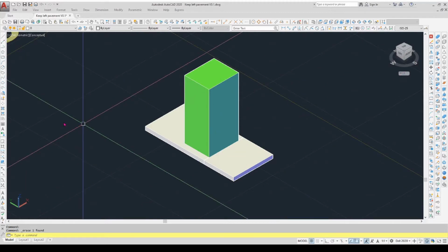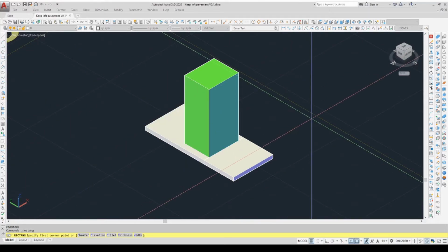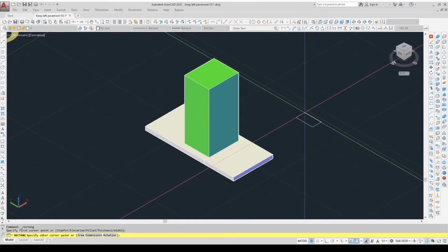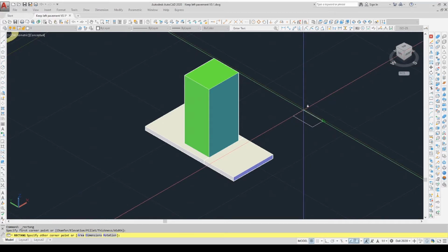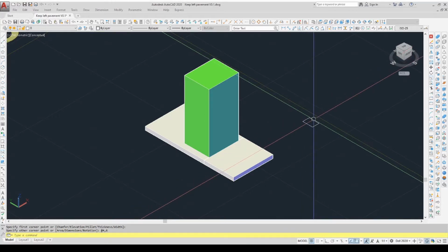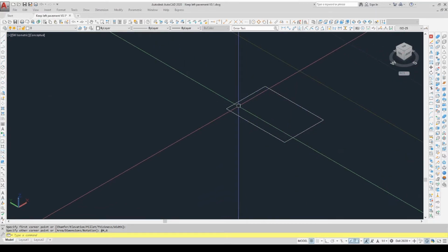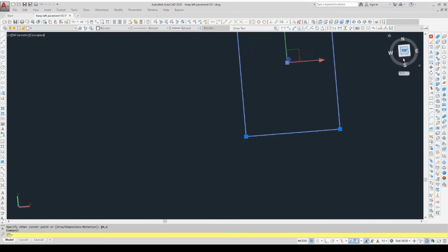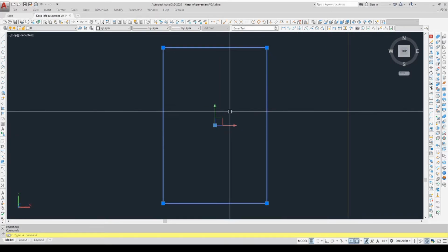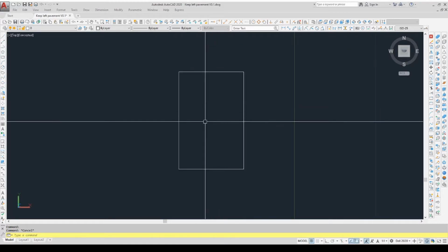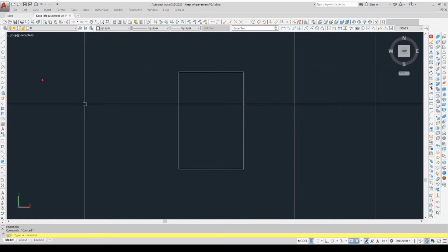Okay, so the basic dimensions of the curb stone is that it's about 6 inches tall and about 4 inches wide. So we're typing 4 by 6 as a rectangle, and then what I want to do is to cut a chamfer here. Let's turn this on its top so that you can see what I'm talking about. That's the cross-sectional area of my curb stone.